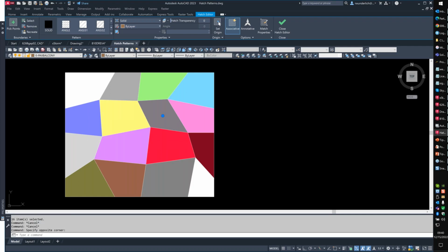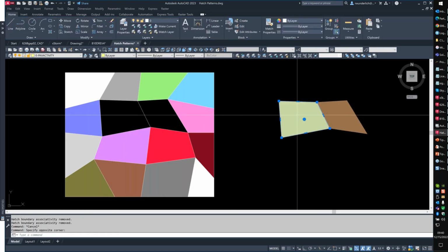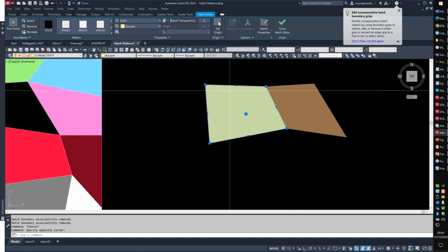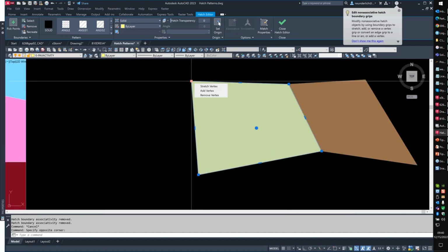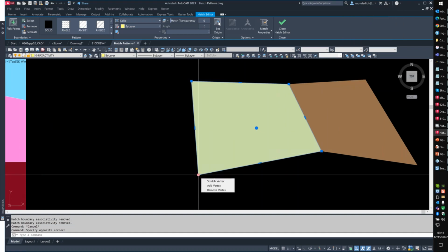Mark, that is right. Option for broken hatches: regenerate the hatch boundary, line work shrink wrap to create closed boundaries, rehatch and get cumulative. Yes and no, that does work most of the time, but you still may have multiple vertices here. So if I happen to move this hatch out here, and you'll see it's now a broken boundary, I can do that process. But if I do not see a vertex pop up on one of these, that means that there's a duplicate vertex here.